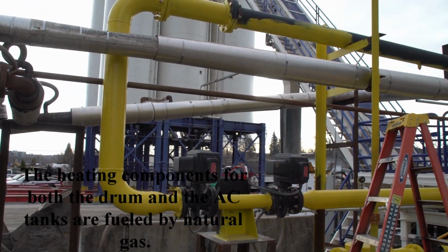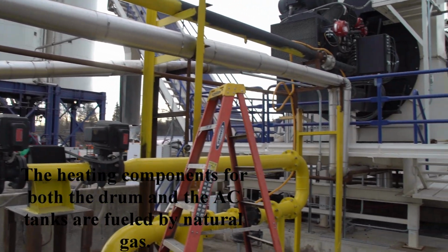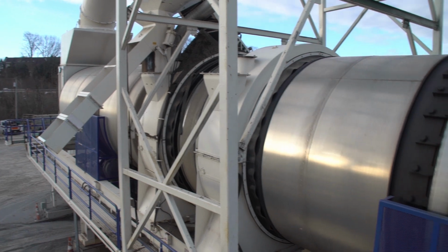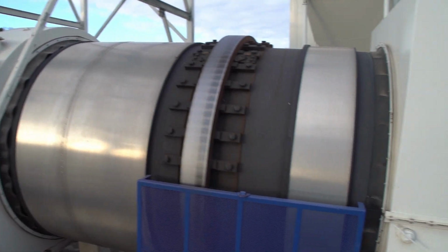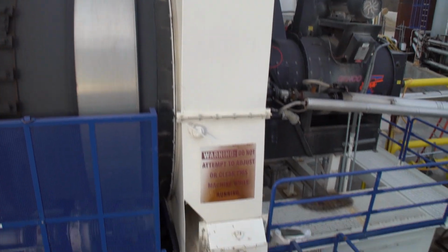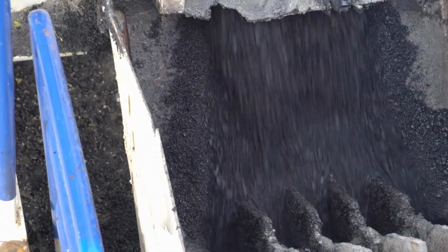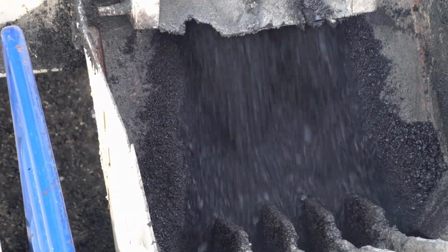We have a hot oil heater that is able to heat all the lines and the tanks to keep them at the right temperature. Once we are making the mix, we will select a tank to pull from. The material will then be pumped and metered into the drum to mix with the material.